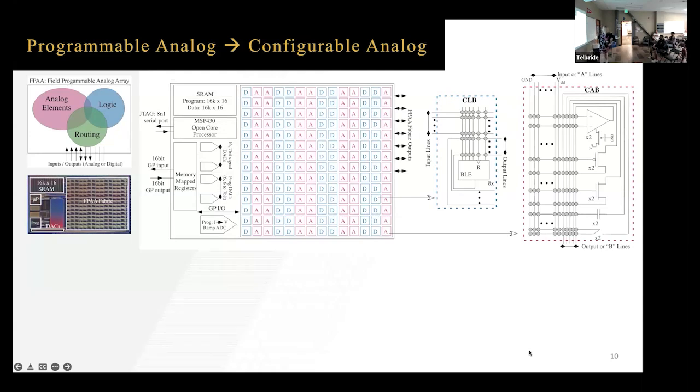when we put this whole thing together, there are definitely blocks for analog components that actually have routing. There are different components in here. There are examples of transistors, capacitors that are floating. There's plenty of capacitors to ground if you like. So we have to work off that. There are T-gates. There are transconductance amplifiers, but what's also nice is the current sources are actually programmed internally. There's a couple different flavors of these, one of which are floating gate inputs and ones that don't. I'll explain a little more of that as we see an example.